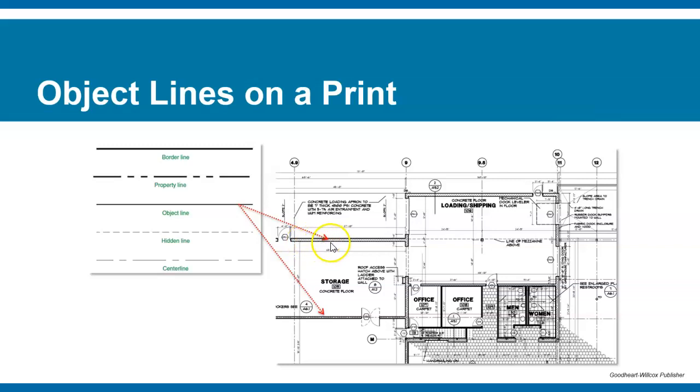And that wall might not be solid. It might be hollow and be filled with something. It could be airspace. It could be insulation. It could be filled with concrete. So that's why there's a hash mark inside. If you see another line inside, crisscrossing inside, it's showing you that this object is filled with another piece of material that's taking up that space.